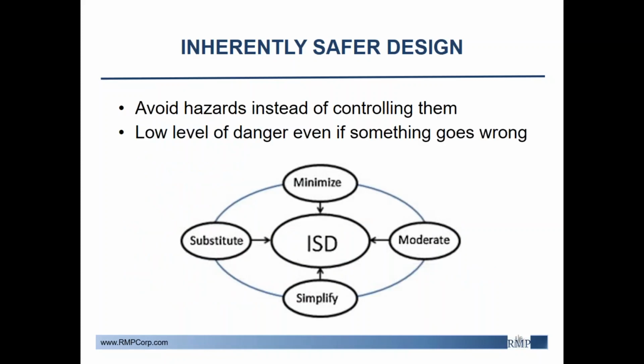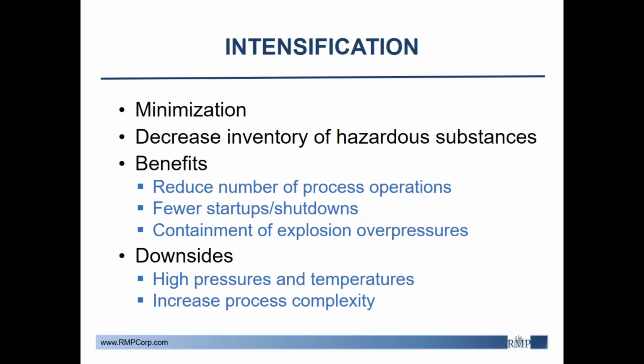The main idea of ISD is to avoid hazards entirely, rather than installing and implementing systems to control them. Additionally, we want to minimize the severity of consequences even if something does go wrong. So we'll start off with intensification. Intensification is also referred to as minimization, and it involves decreasing or eliminating the inventory of hazardous substances.